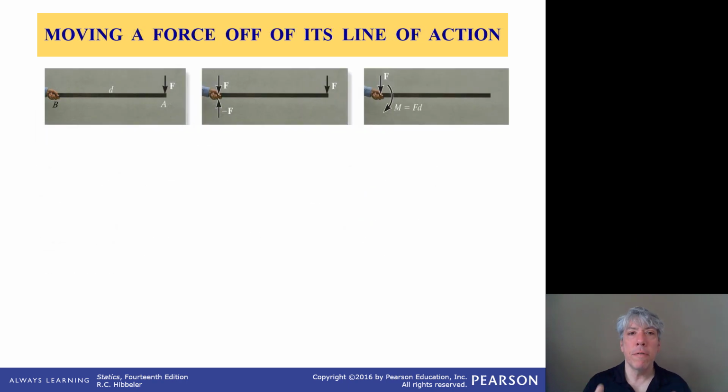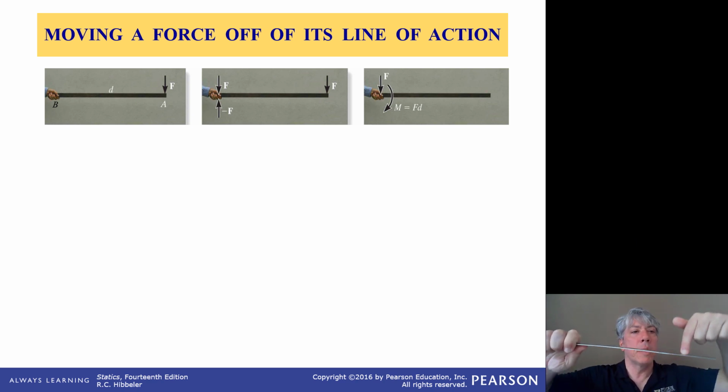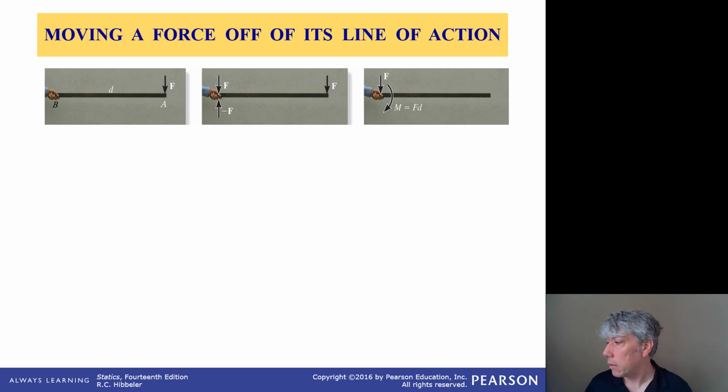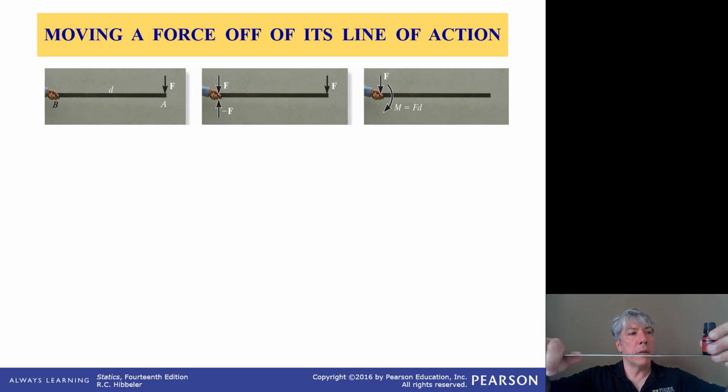Now, if we move a force off of its line of action, then we have to add in a moment. So if you take a pencil in your hand or a ruler or whatever you have there and hold it and feel what it feels like to put maybe a constant weight at different points along the length of that line. Let's try. Let's see, what have I got sitting here? Something to make the house smell good, okay? So you can feel the effect of putting this force at different locations. What you notice is that the amount of twisting that this load does is much greater here than it is here.